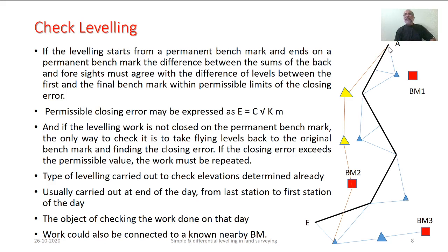Here again we can adopt the fly leveling. Intermediate stations can be made totally obsolete. Hence, the computed value and the value from which we started the work should be lying within the permissible limits, which is nothing but the closing error.